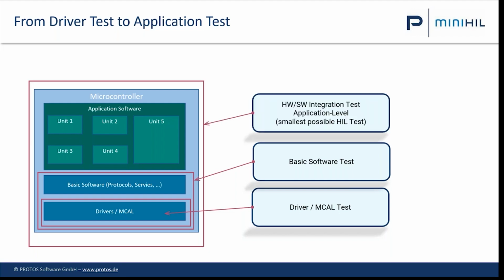And the highest level would be a hardware-software integration test. So application level test, but including the basic software and the drivers. So that's the smallest possible hardware in the loop test on microcontroller base. So the idea is here to test at the pins of the microcontroller, but the complete software stack.